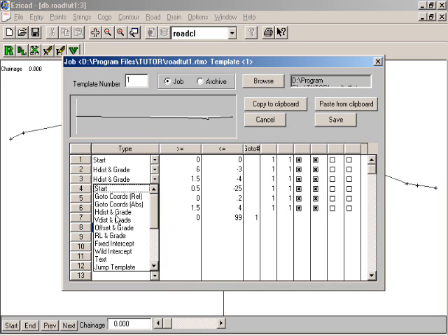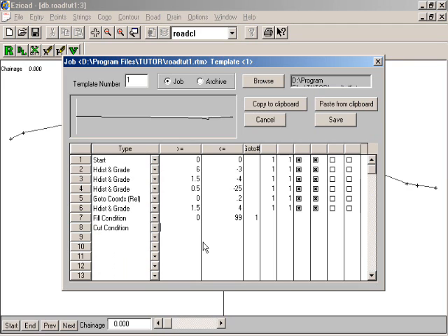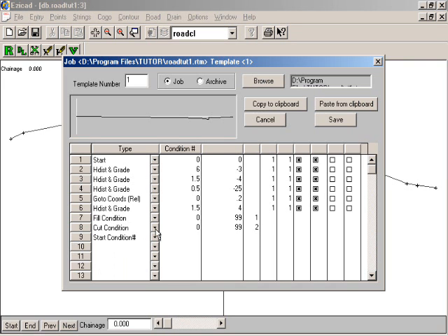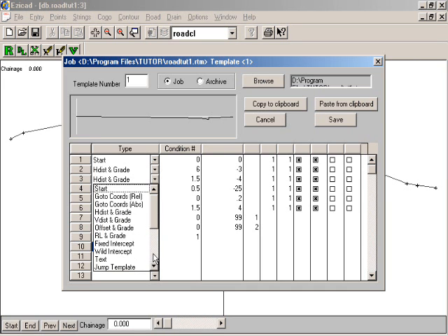At the same time set a cut condition at this point and branch that to condition number 2. Basically this gives you the flexibility to alter the individual things later on. Once that's done, it's time to start condition 1, so go down and find start condition and tell it to start condition number 1. And condition number 1 will simply be a fill batter at grade.